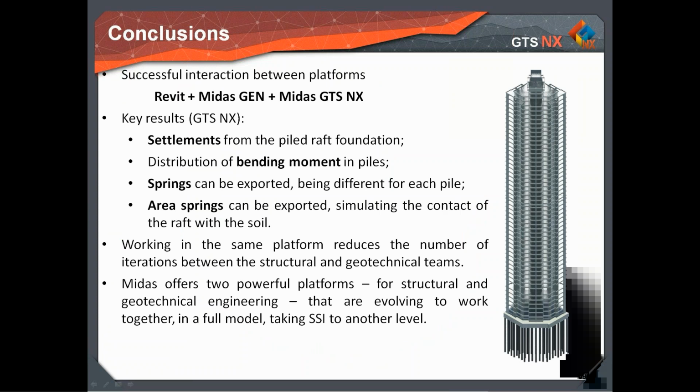Finally, some conclusions. We consider that we had a successful interaction between Revit, MIDAS Gen, and MIDAS GTS NX. The key results from MIDAS GTS NX that we have analyzed are, firstly, the settlement of the Piled-Raft foundation, which might be inside a range of the tolerable settlements for this kind of structure. For interaction with the structural team, springs can be created either for each pile and also as area springs, which are the contact of the raft with the soil.